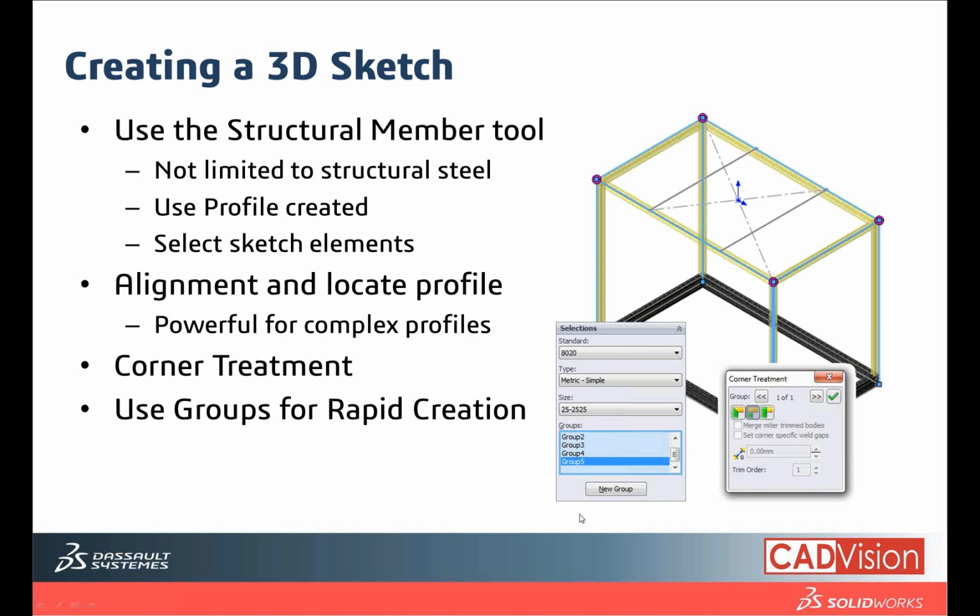bottoms. But once you click on that, it might change only one corner of it to your desired output. But don't worry about that. If you notice this connection pin, this weldment point, you can always click on each weldment point and a little window will come up called the corner treatment. You can select from this to get your desired outcome of joining.